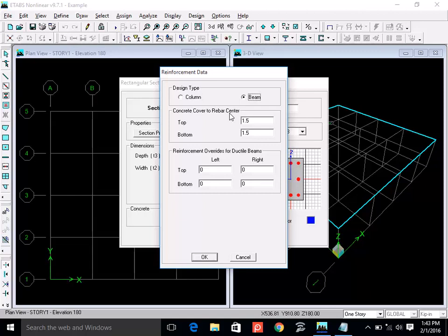But I think you learned this, number 10. After number 10, you have number 13, I think. And this one, the longitudinal bar, has variation. Longitudinal bar in beams is generally either number 13 or the next one, number 16, up to number 20.